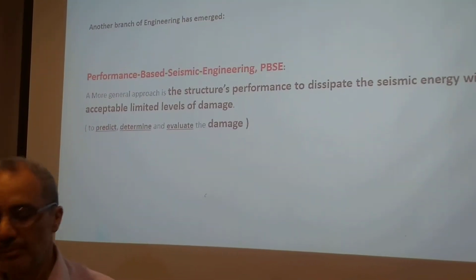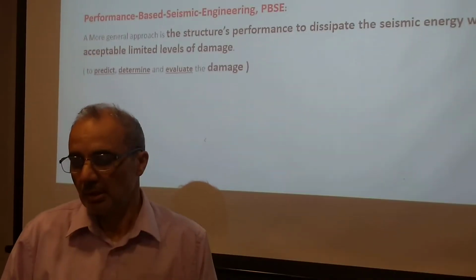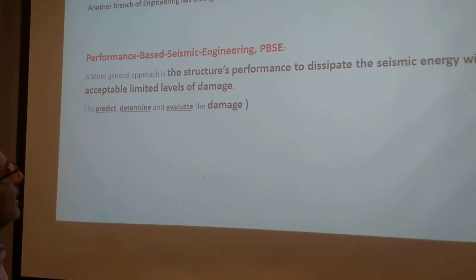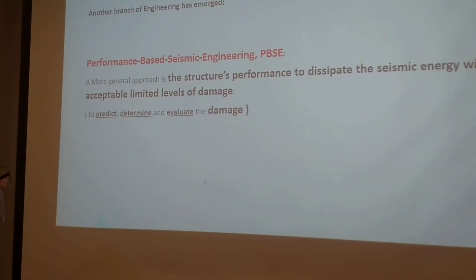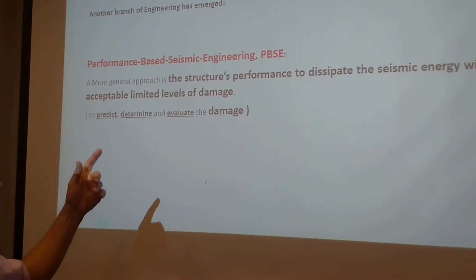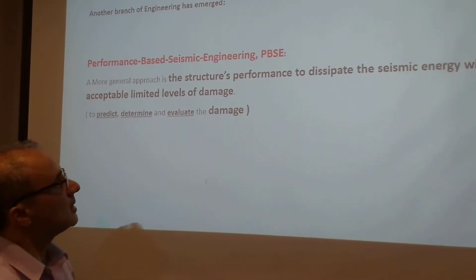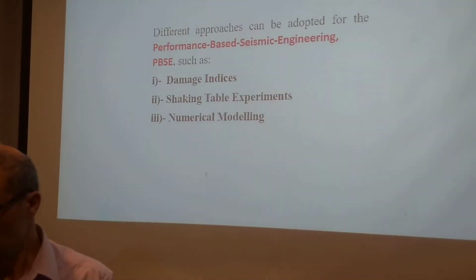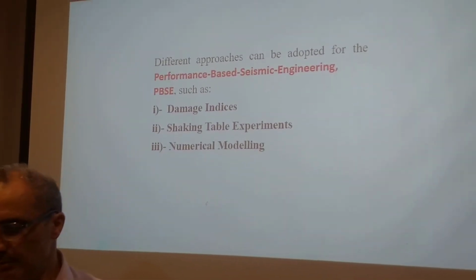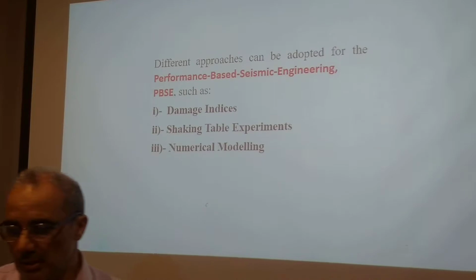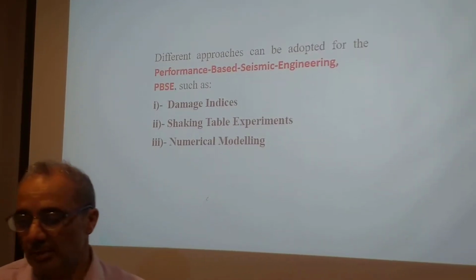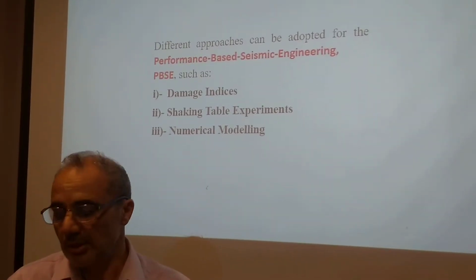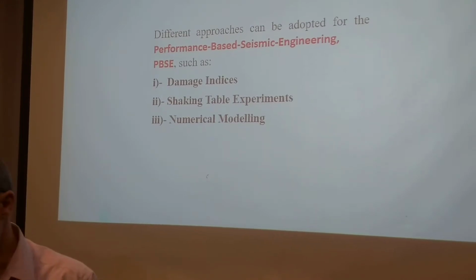Now, because of this, another branch of engineering has emerged. It's performance-based seismic engineering, which is PBSE. The definition of performance-based seismic engineering is the structure's performance to dissipate the seismic energy within acceptable limited levels of damage. Now, there are topics in PBSE which an engineer should have some knowledge about: the damage indices, the shaking table experiments, and the numerical modeling.